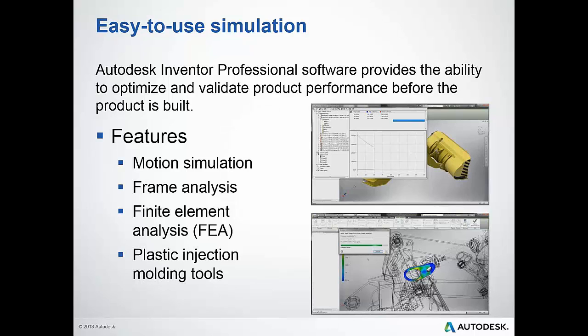So it has all that intelligence in it now. When you fill a plastic part, you can see if it's going to have any cooling issues that cause defects on the outside surface because of strengthening beads or ribs that you've added, and it'll also tell you whether the part's going to warp or not. So it's a great tool. Rather than find that out after you've built a couple of prototypes, it's nice to find it out before you've even put it out to a die. So again, for plastic injection molding, there's just a lot there.